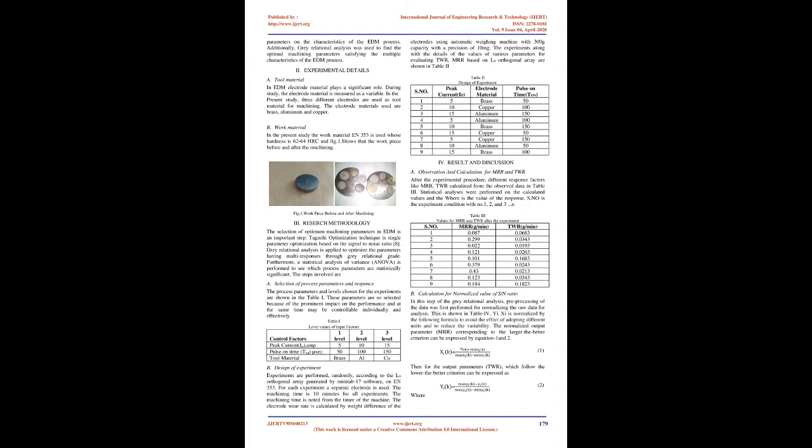This study presents experimental analysis based on 3 factors and 3 levels orthogonal array L9 design. The objective of this research is to study the performance of different electrode materials on N353 workpiece with EDM process. N353 is a high-feature alloy steel giving good ductility and shock-resisting properties combined with resistance to wear. This steel is mostly known as bearing steel and used for bearing production in industrial sector. N353 steel is chiefly famous as bearing steel.